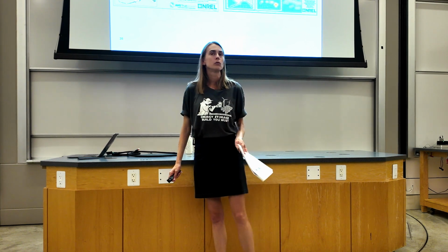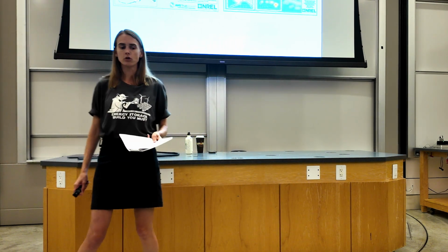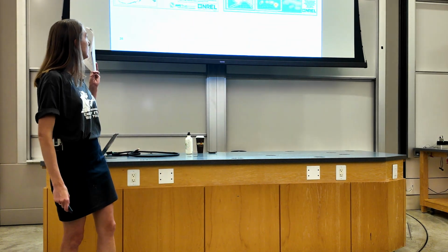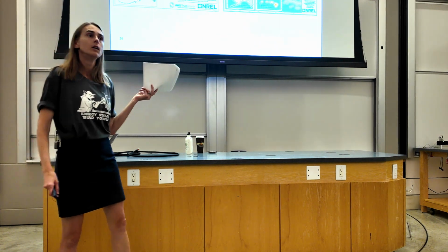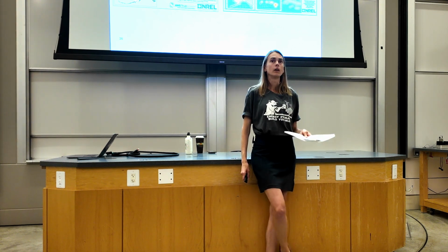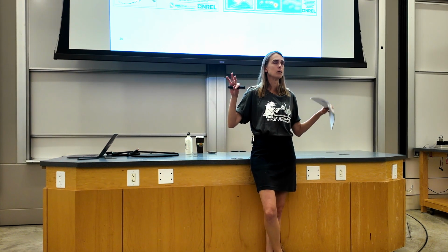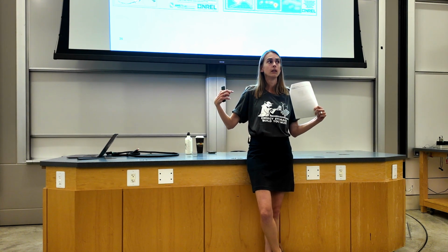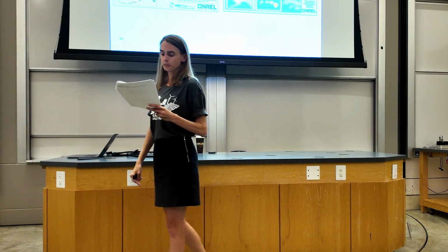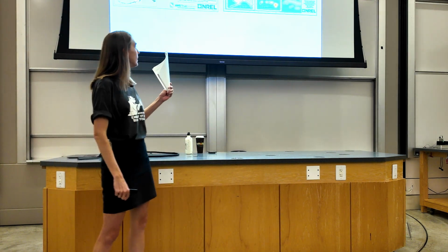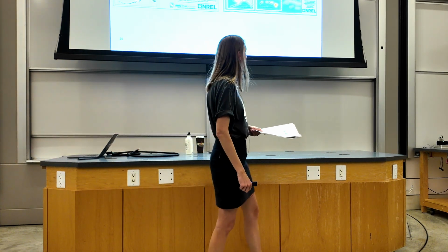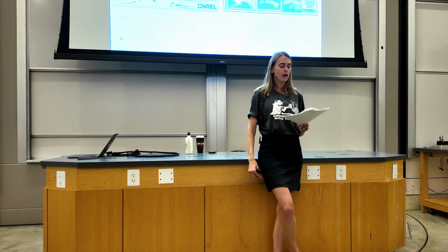And the way that we figure out how much resource is in a given location, we can certainly look at maps like these. In the case of wind energy, you definitely want to measure site-specific wind energy resource using a met tower with an anemometer and whatnot, because local terrain can really impact the wind energy, including at different levels of height. For solar, maps like that come out of NREL are really good for assessing the solar resource at any given point.